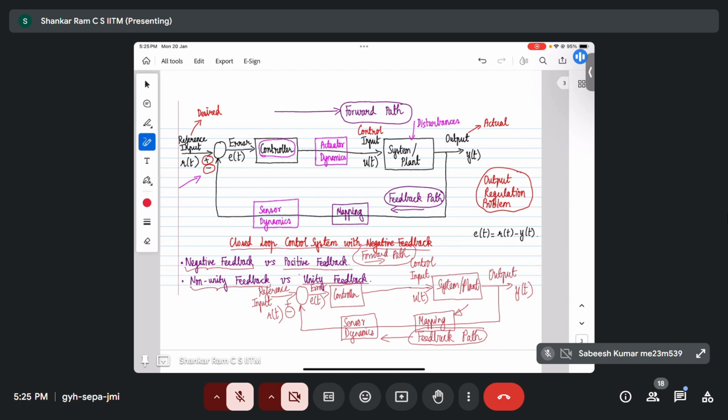Similarly, let us say I know that there is a speed difference, and I know that I have to adjust the voltage given to the motor. Then the controller calculates a voltage change. But the question is, how soon can I implement the voltage change through some electronic circuitry? That is what is called the dynamics of an actuator. How fast would I be able to have an actuator which will implement the control input that you and I desire? So the actuator dynamics also becomes important.